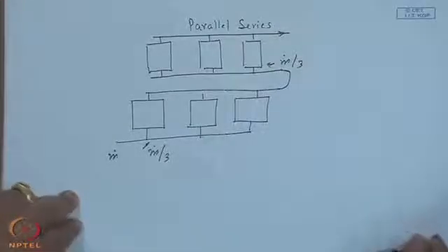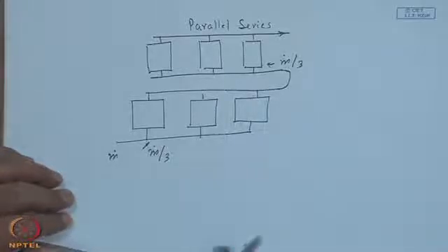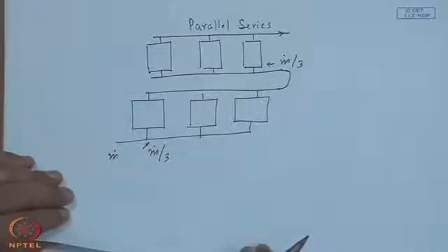So, these are the issues when you talk about not a single collector like in the classroom. We have a large system supplying thousands of liters of water, which may have 2000, 3000 square meters of collector area, with about 1000 to 2000 collectors of each 1.5 to 2 square meters of area. For n number of reasons, one has to connect them in parallel or in series or series parallel combination. If they are all in series, first of all the land area, geography or topography has to be suitable. Of course, it is not that I cannot put it side by side and still make it series, but then one has to worry about the losses through the pipes also. So, apart from the land restrictions, one has to really work out through a simulation or a calculation procedure what gives you the optimum heat transfer enhancement or advantage vis-a-vis the additional pumping requirement.